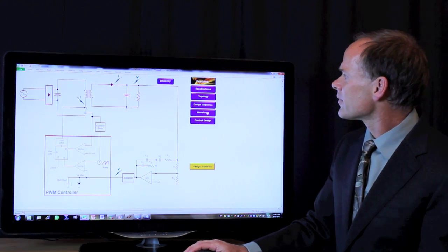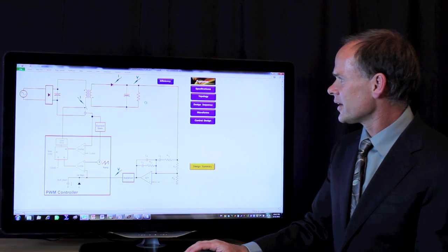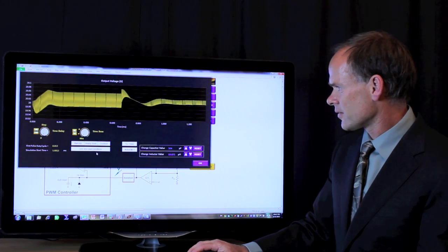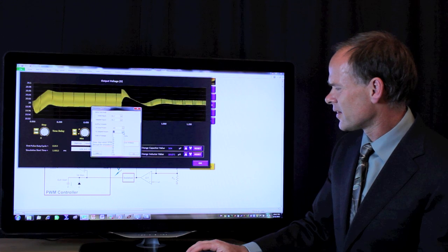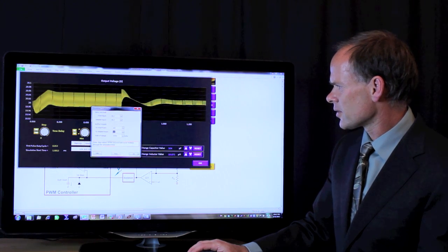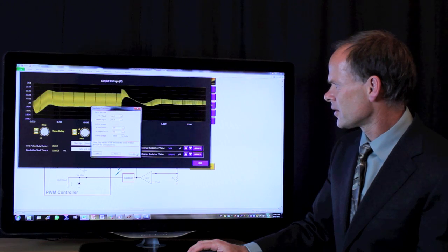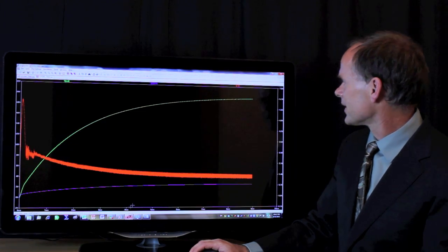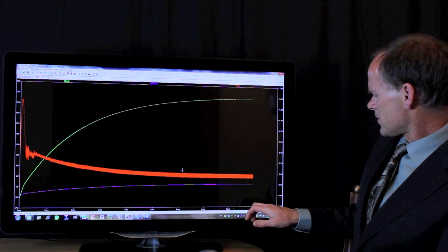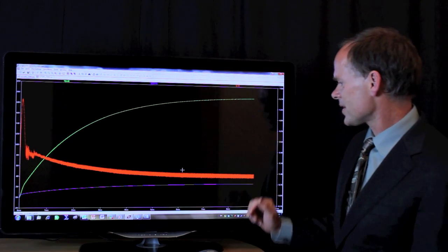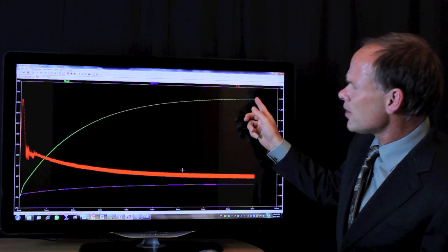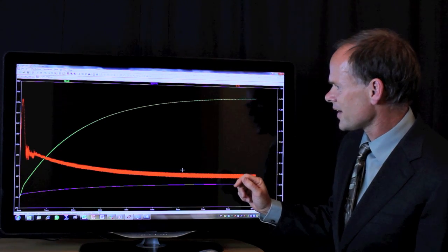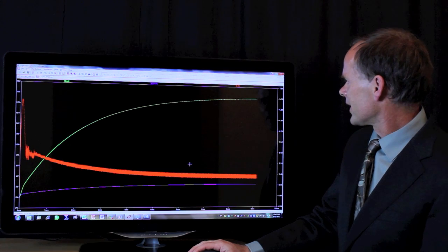and look at the waveforms, the output voltage again, and let's get rid of our step load response here. Back to 100% step load. And just before we take another look at this, let's see how LTspice is doing. It's coming along here. It's just about at 9 milliseconds now, so we've got 1 millisecond to go. We can see we've almost reached the 20 volt threshold where the converter is regulating. And it's all looking fairly good.